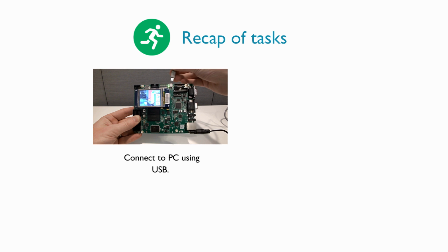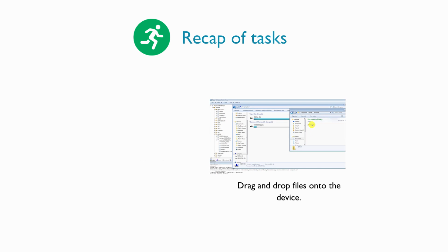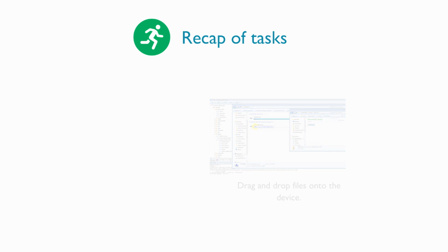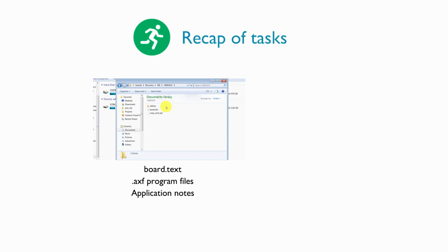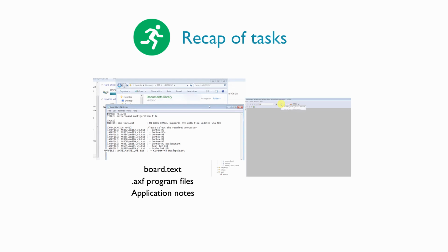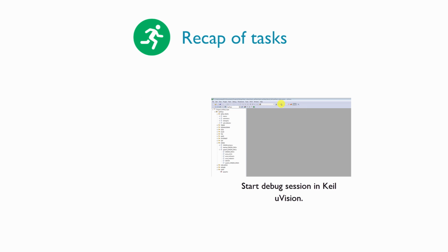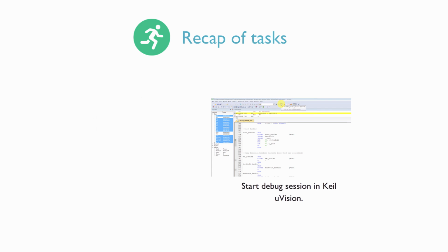So at this stage we've shown how to transfer files to the board, which files are important when configuring the board and uploading your own designs, and how to connect the board to the Keil debugger and download and verify the code.